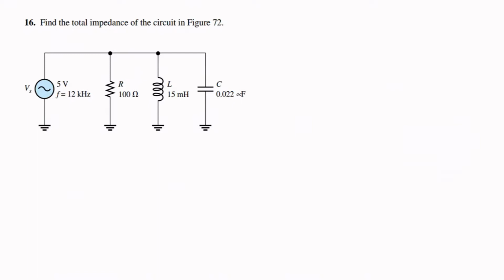Why are we plotting the current instead of the voltage? First of all, the voltage across each of these circuit elements is the same, so it does not provide as useful information. If we plot the current instead, we also get the magnitude, but if we just plot the voltage, then all magnitudes are the same and we just get the relationship of the phase angles relative to each other. So in parallel circuits such as these, it's better to plot the currents for the circuit.